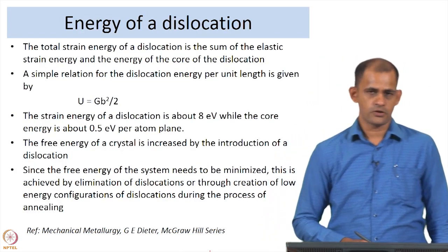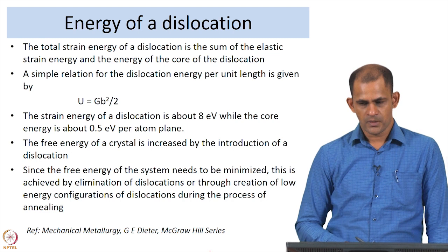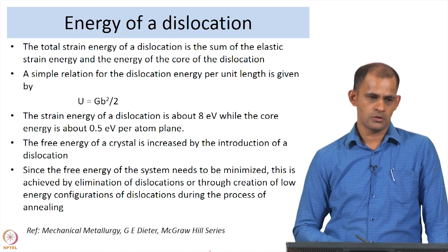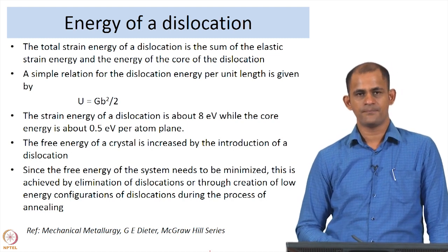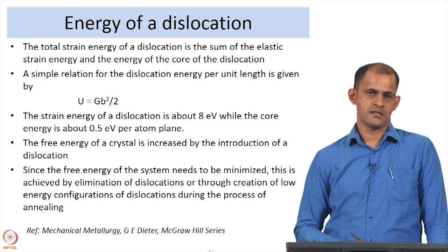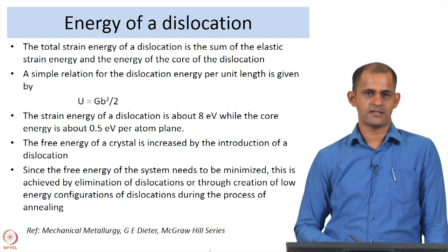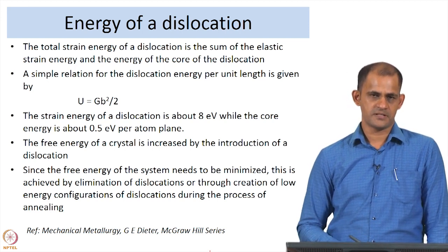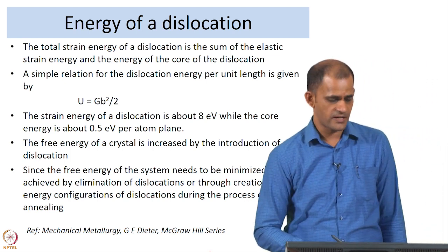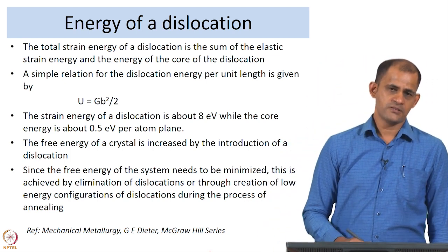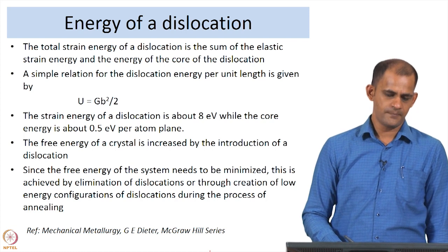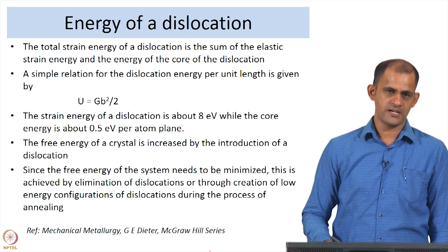So, the energy of a dislocation. We are talking about how temperature can play a role in changing the dislocation configuration, and the role of temperature can be understood by discussing the energy of a dislocation. There is a stress field around a dislocation, and the strain associated with the stress field results in the development of a strain energy.